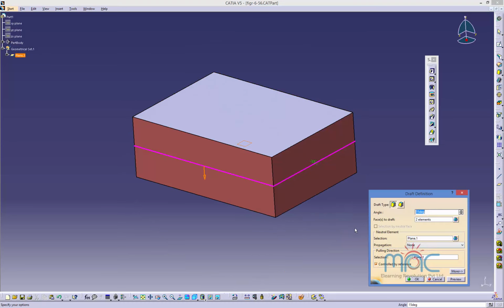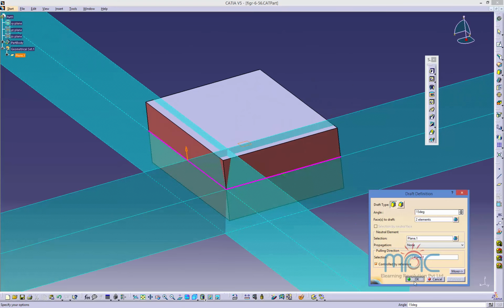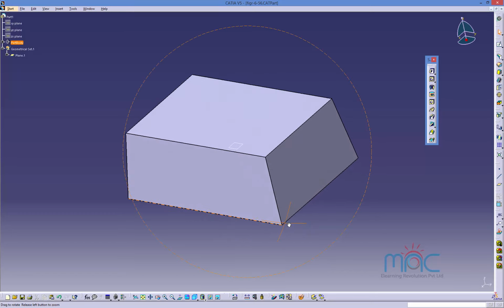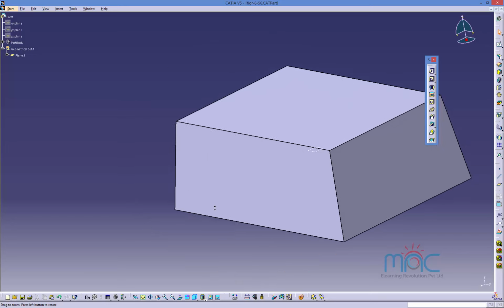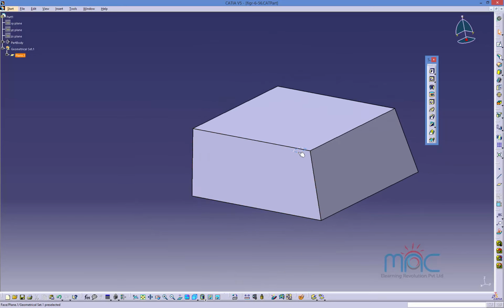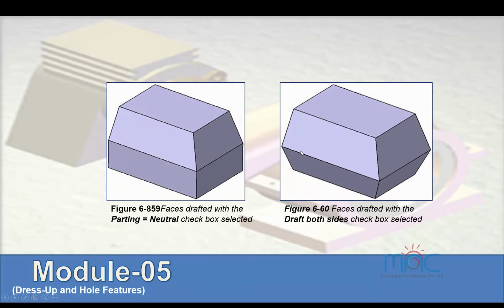And if you double click this, you have the reference where you can switch the directions and see the preview. And the draft will be like this also. Draft angle can be flipped towards downward or towards upward, and you can also control it. So for the draft you could refer to one neutral plane, which could be your datum, which could be the plane which you have defined. So this is one aspect which we understood here.